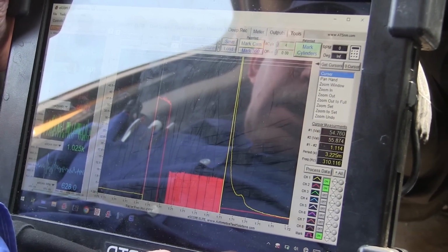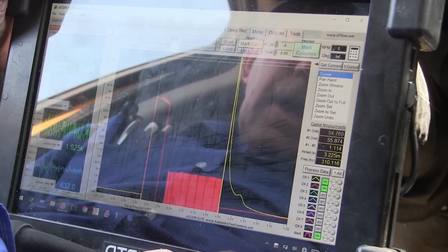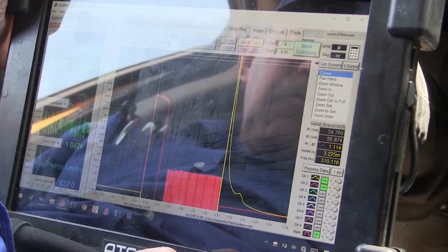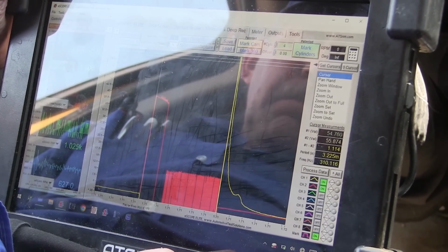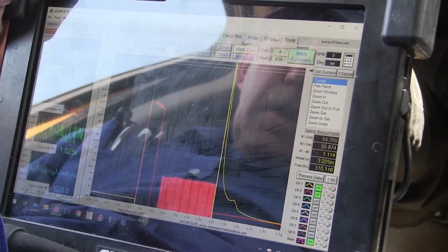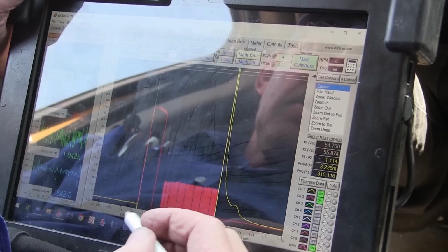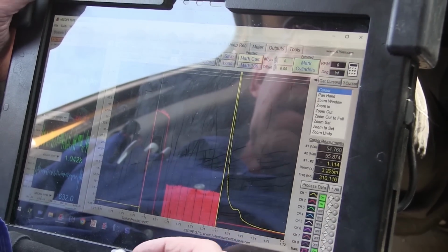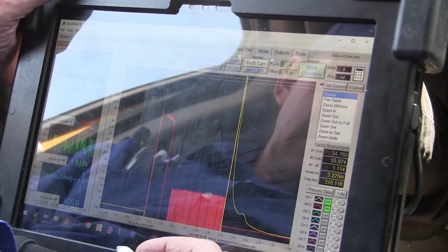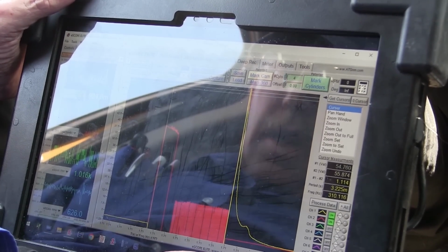So I've got a lot of on time at idle, and it doesn't go up that much. So I could actually have the trim values that we're seeing where we go from 40% to 20%, and it would be non-linear. And the way that the control system is done with the pressure on this GDI could definitely, if these injectors are the wrong injectors, I could be having this problem. Very interesting problem, guys. Let's go back over to the shop.